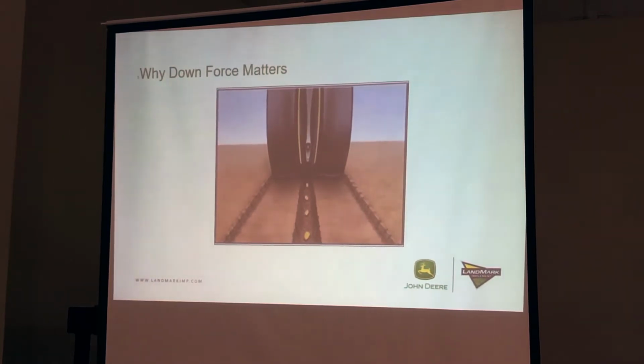Running too much downforce will cause excessive wear on the openers and gauge wheel bearings, shear rivets on the True V hubs, and more importantly can cause compaction of the seed trench sidewalls, resulting in poor root growth.